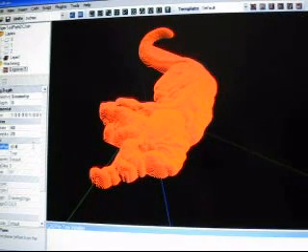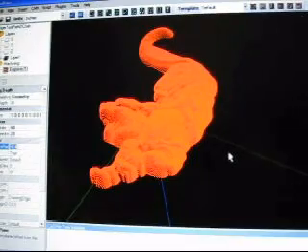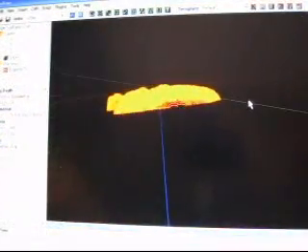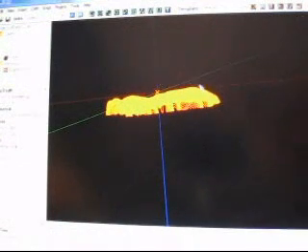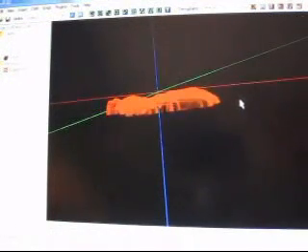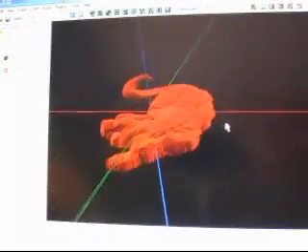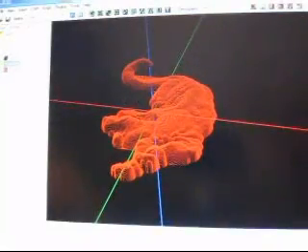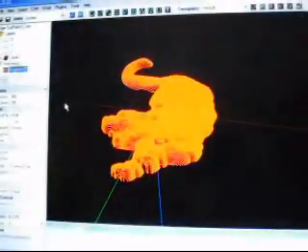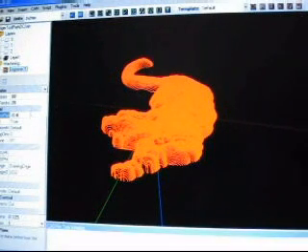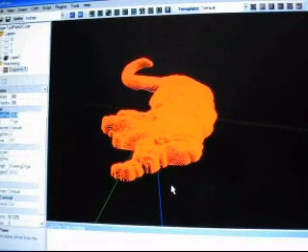The clearance plane. Normally I would set my clearance over the part. I usually set it to like 0.1 of an inch over the part. But here we're going to set our clearance to our floor depth, which is, as we know, minus 0.4 of an inch. That's the deepest cut that this thing is going to make.